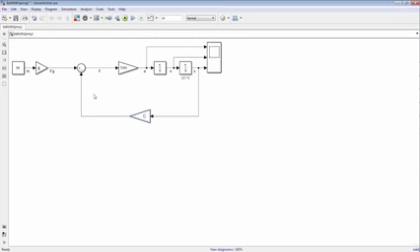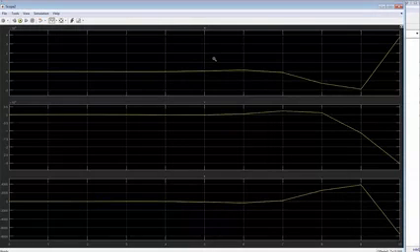Good. Now it's a good time to run the model. Okay, let's run this thing. Oh, this looks strange. Whenever you have such straight lines in a simulation of a continuous system, chances are very high that your fundamental simulation time step is too big. At the moment, it's got a time step of 1 second. That's much too big, I think.